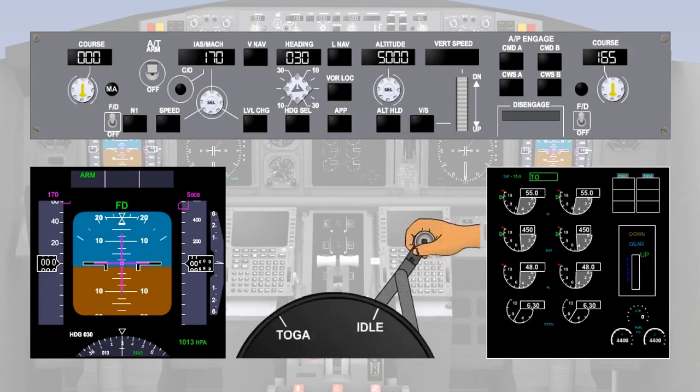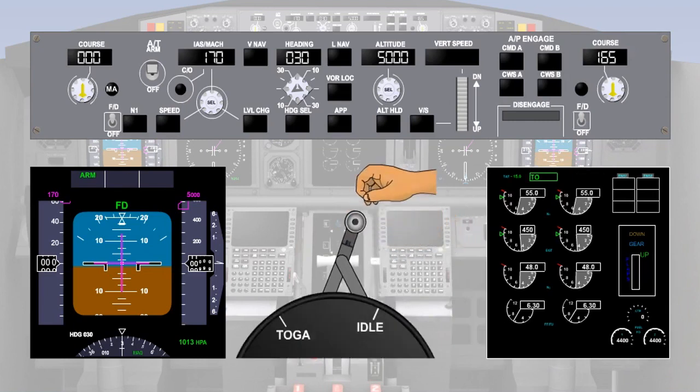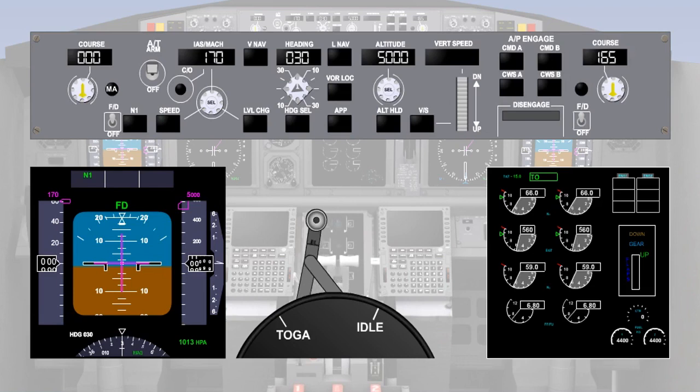After lining up for takeoff, the throttle levers will be moved manually to approximately 80 to 85% N2. And the autothrottle is engaged in thrust mode by pressing the TOGA switches. Thrust or N1 is annunciated in green on the flight mode annunciator. The autothrottle will now advance the levers until the takeoff thrust is achieved. After 60 knots, the autothrottle will hold the levers at that position to maintain the selected value and to prevent the system from chasing any slight variation in N1 or EPR during the takeoff.